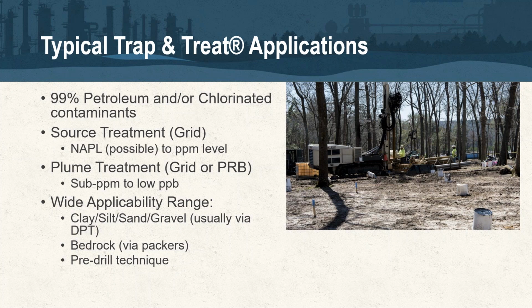And from a geology range, we also have a pretty wide applicability range, dealing with your typical overburden lithologies, clay, silt, sands, gravels. What's going to change there is going to be your design, right? Maybe your injection spacing, your volume. All of those may change depending if you're in a sand site or a clay site, for example.